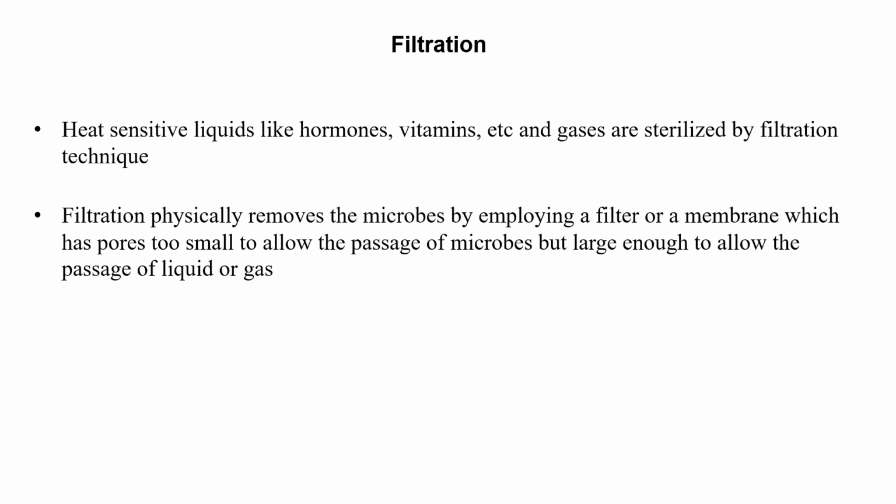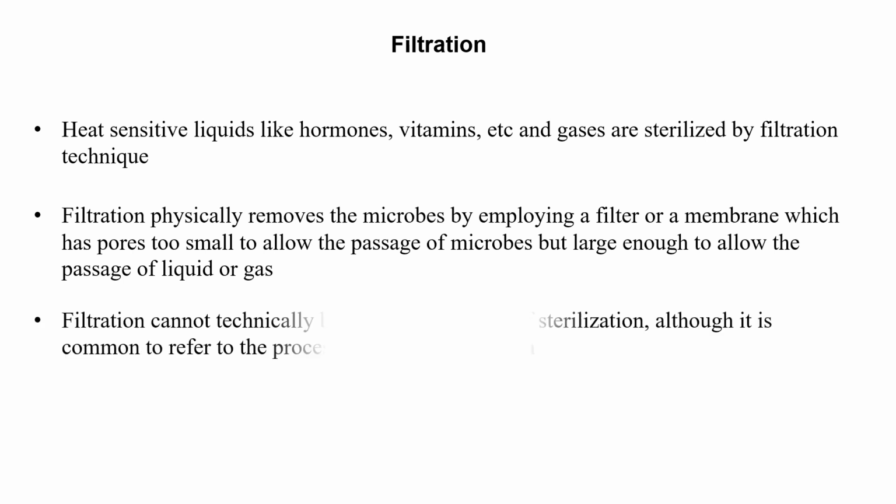But a filter of this pore size would not remove viruses because they are smaller in size. A filter system with sufficiently small pores to remove viruses would have an extremely slow flow rate due to the viscosity of water. Because viruses are not removed, filtration cannot be technically considered a form of sterilization, although it is common to refer to the process as filter sterilization.